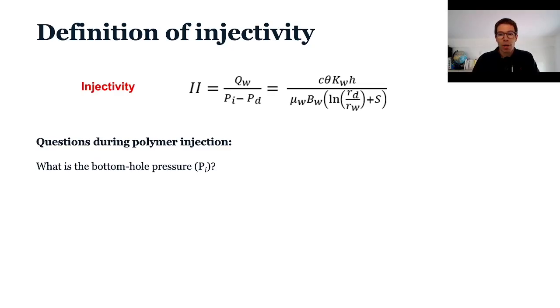It's well known by the people in the fracturing industry because polyacrylamides are used to decrease the pressure drop. So you put a little bit of friction reducers into the water, anywhere between 50 to 350 ppm, and you will observe a pressure drop decrease of 50 to 70%, depending on Reynolds number, concentration, water quality, etc.